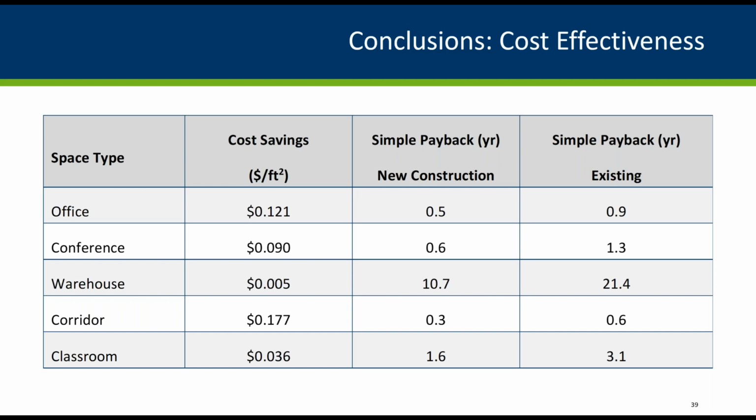Due to these short payback periods, we recommend that for the remainder of the space types that task tuning be implemented in new construction projects or major renovation projects in which a dimming system is already planned as part of the design. For the same reason, if a dimming capable system already exists in a facility, task tuning should be strongly considered to achieve cost-effective energy savings.